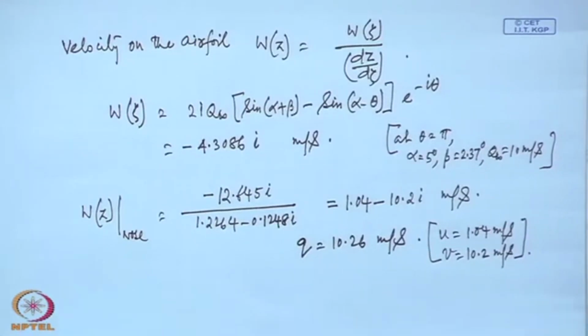I think I earlier told you how the pressure acting on a body is measured. You have not done any experiment as yet. See, on the surface of a body, a very small hole is drilled, okay, and then some probe, usually it is just a tube, is inserted through the body, so that it is flush to that surface.